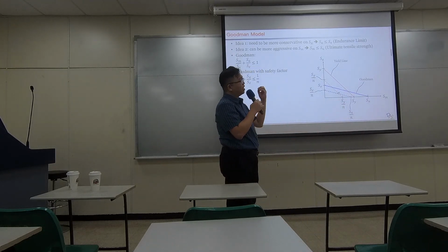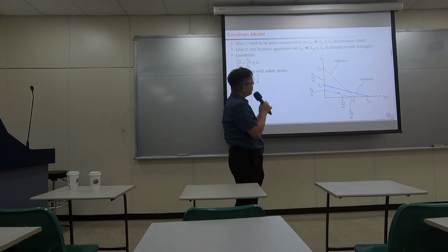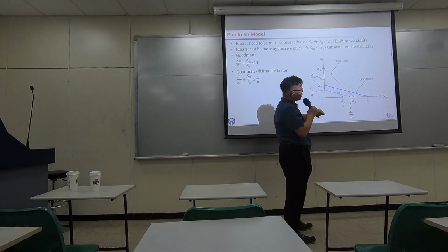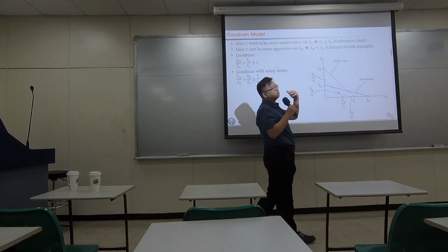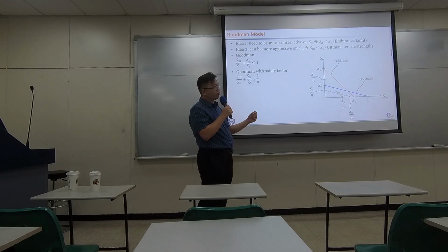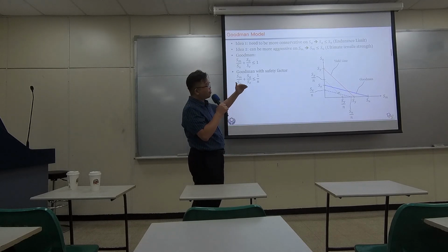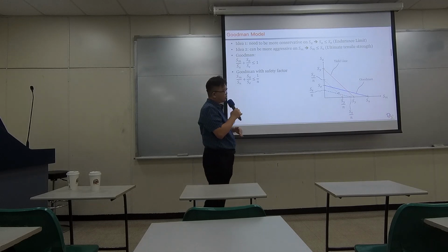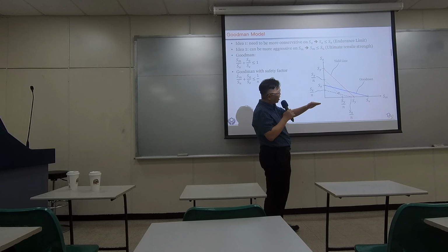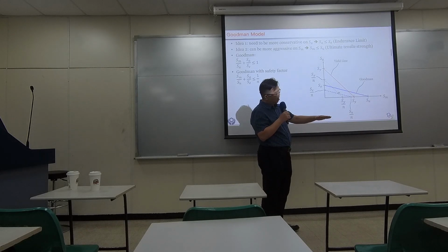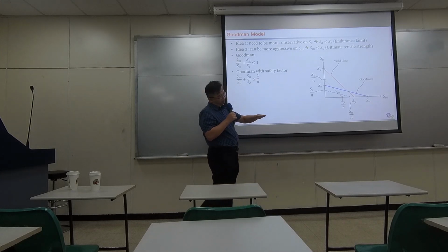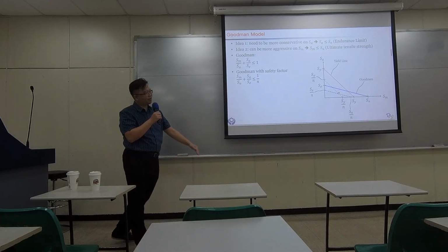Now, in the idea of fatigue, we know the strength of the material will reduce when we have cycles of loads. When the cycles of loads increases, the strength decreases. So for metal, there's like a saturation point, like a minimum point, minimum strength.